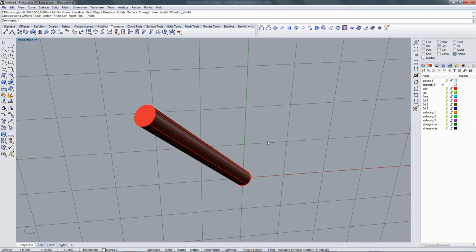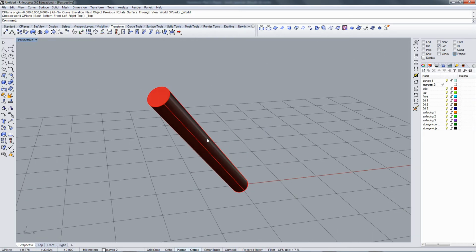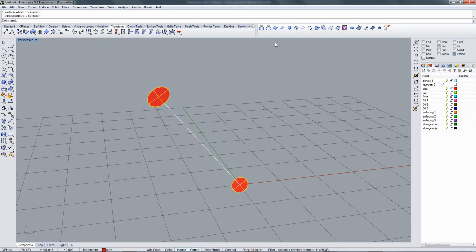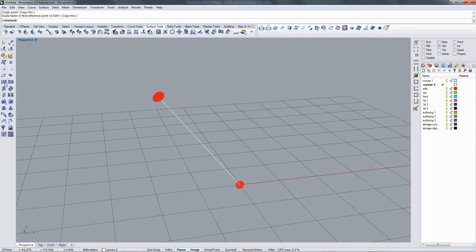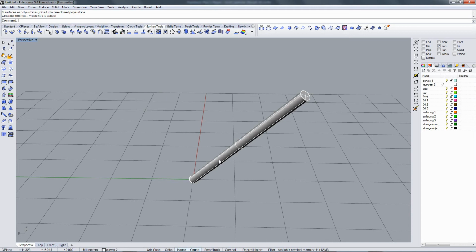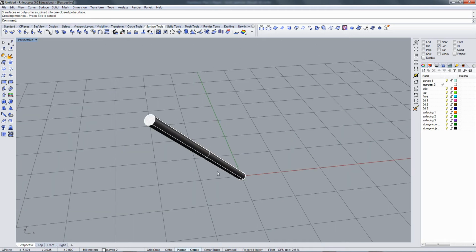Now, I'm sure that somewhere in the listening audience we have an advanced Rhino person who will say, well, I don't have to do any of that. I can just explode this out, duplicate the borders. I don't even have to duplicate the borders. I can just scale each one of these. Scale 3D this time. And then a loft in between them to reconstitute the shaft of the wire. Excellent. That worked. Gave you exactly what you wanted. But that's not the point of using a scale transform. Okay? I specifically said scale.